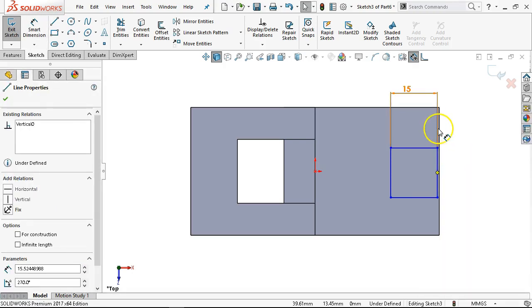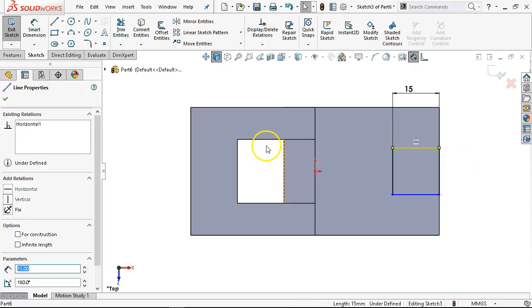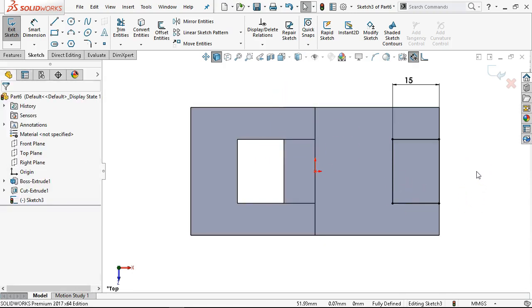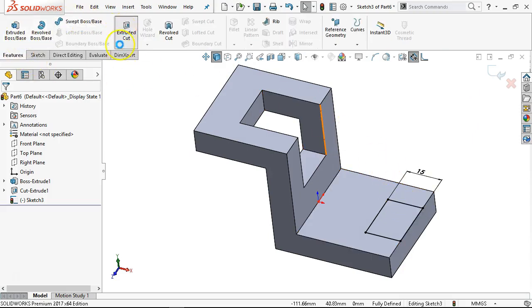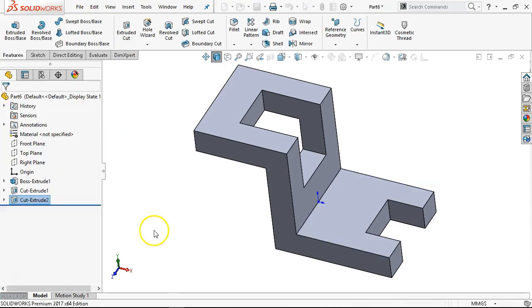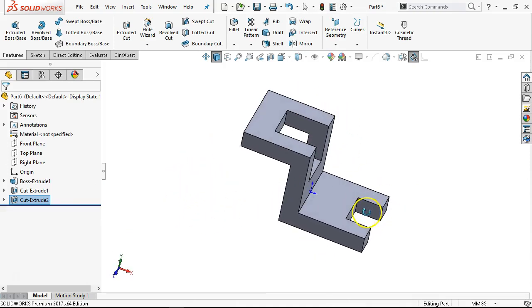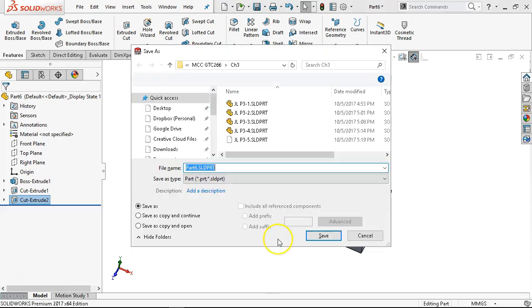We're going to select the midpoint, select the edge, make the midpoints, and then because of the ability to project, I'm going to make those collinear. So now the dimension in this sketch drives the geometry in this sketch. Whatever this fits into, whatever function, what I'm saying in my design intent is that these notches will always be the same. If I find out different, I go in the sketch, I remove the relation, I put in a separate dimension.